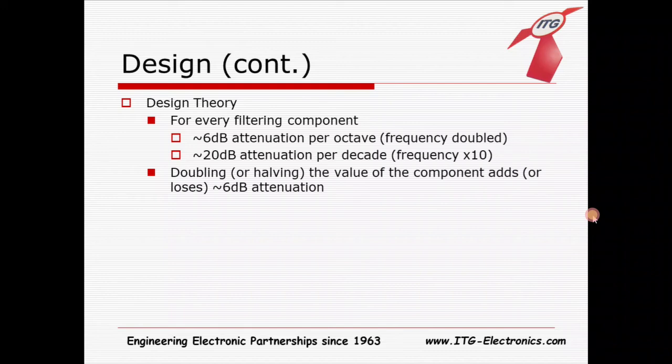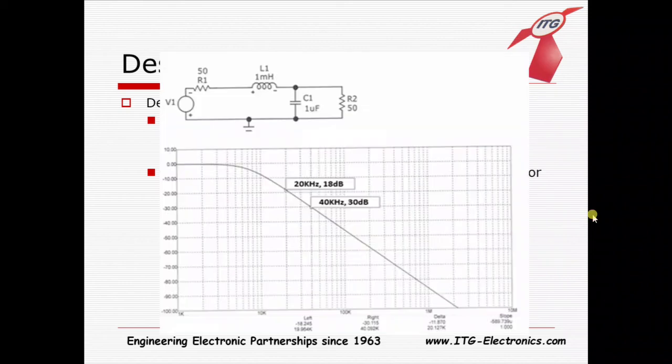If you're expecting, let's say, a 500 millihenry inductor to perform a certain way, but really the attenuation you're getting is maybe 6 dBs less than that, you can expect that roughly half of the inductor's inductance is being lost to that current saturation of the core. And maybe it's only reading at about 250 millihenries when the system is actually running at full current. So situations like these are useful to have these kind of rules of thumb with design theory.